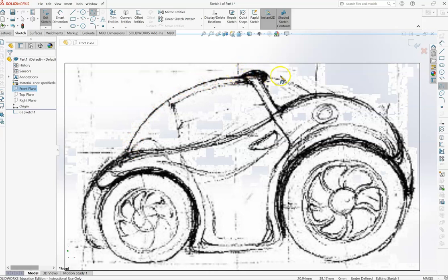And around to the back of the car, down below the wheel, I'm going to go straight across here, and I'll show you how to cut the wheels out separately, because trying to get the spline tool to change directions quite as much as the wheel does is going to cause you pain. And then back around. So I'm going to start from this point, go all the way around, ignore the wheel cutouts for the time being, and then back around to this point.